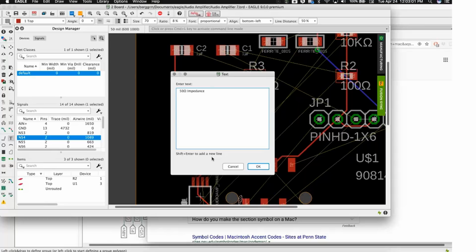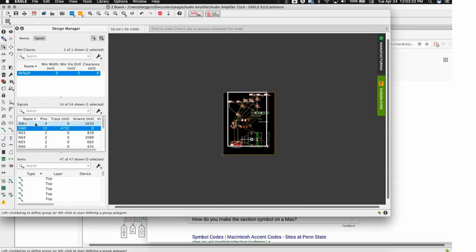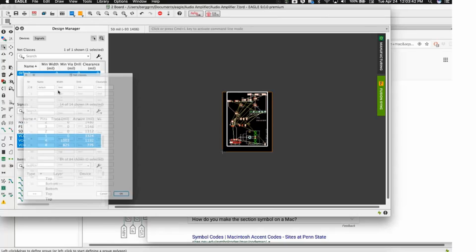Is there work to have DRC ignore the net class when the minimum size and separation are different? Could you clarify that a bit, Haitham? Unless Matt or Ed understand exactly what he's asking, but I'm a little unclear. Yeah, net class when the minimum size and separation are different. Because the thing is, Haitham, both net class and DRC are always defining minimums. The interaction is which minimum is stricter. So it's not that DRC and net classes have priority one versus the other. They're the same class of citizen. The issue is which one is stricter.